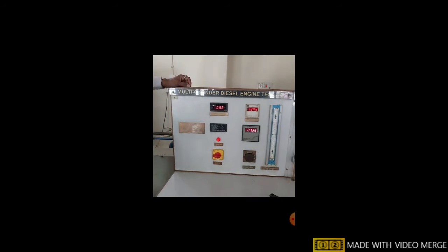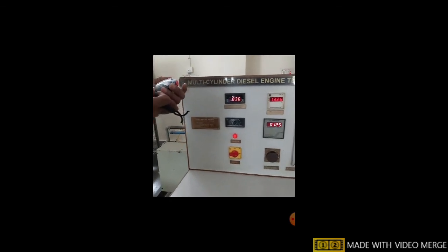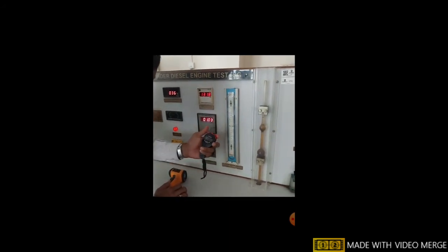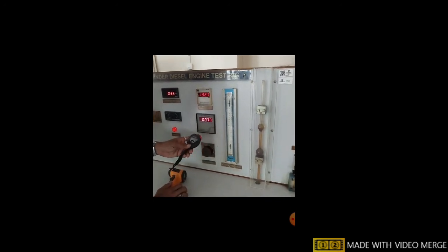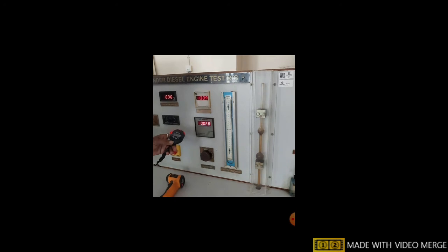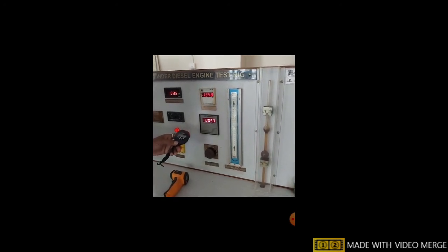So once the load is increased and the speed is decreased, at that moment how much fuel has been consumed, you can notice by using a stopwatch. You need to record the time for 10 cc of fuel consumption. If you know the time consumed for 10 cc of fuel consumption, you can measure the fuel consumption rate.